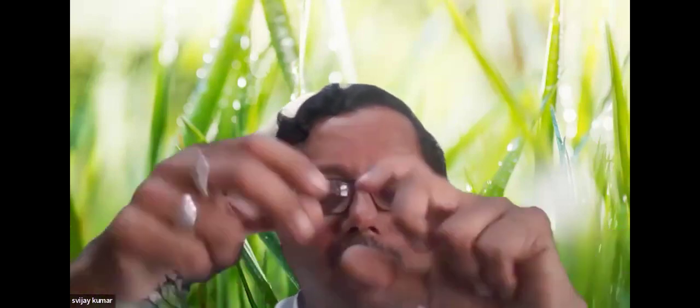Whereas a sprinkler nozzle is relatively very simple, and anyone in the farm who knows how to open a spanner can just open and clean the nozzle and put it back. So it's that simple to operate. Whenever we go to a farm, we always tell them to graduate from flood to sprinkler, get used to sprinklers, and then get into drip. That graduation will help the farmer to understand, and therefore in terms of operation convenience and certain advantages which I have already explained, the sprinkler and rain guns definitely have advantages.